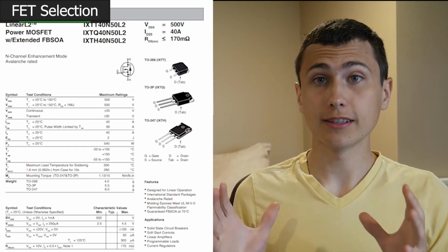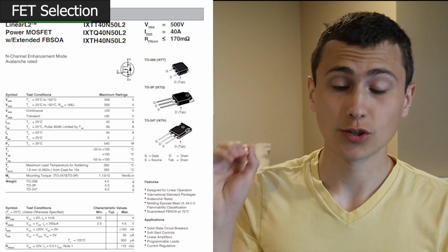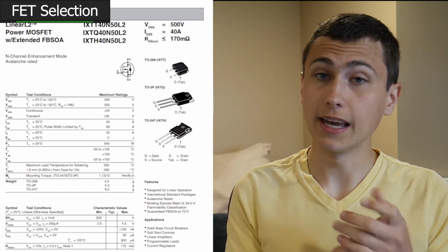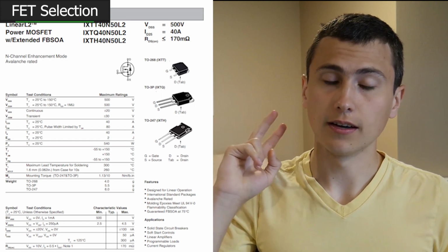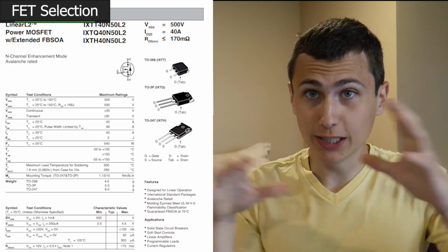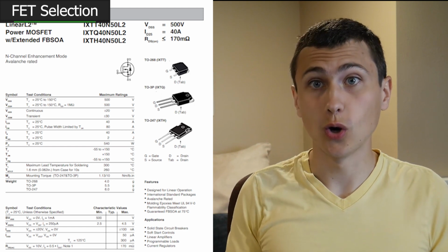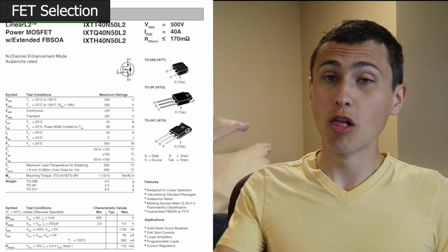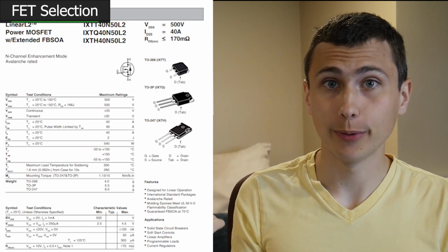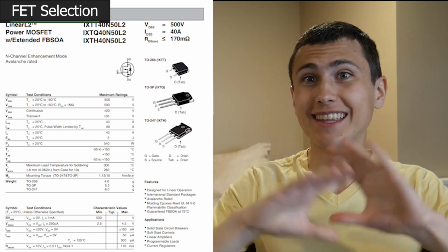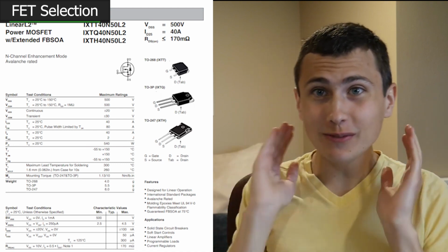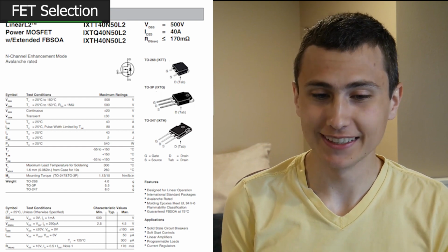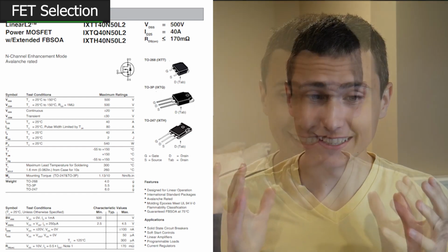The critical thing that this MOSFET is designed for really shows up in two of the characteristic curves. And those curves are the gate charge curve and the safe operating area curve. Just looking at where that safe operating area curve goes, it's pretty obvious this FET is something special, because you don't usually see 300 watts of power burned in a MOSFET as a part of their steady state, this is totally fine, don't even worry about it type of rating. That's not normal.